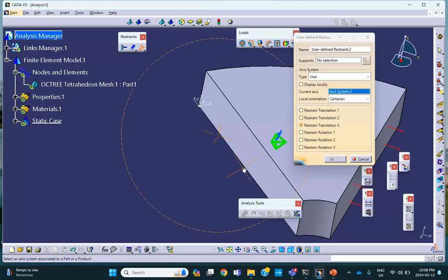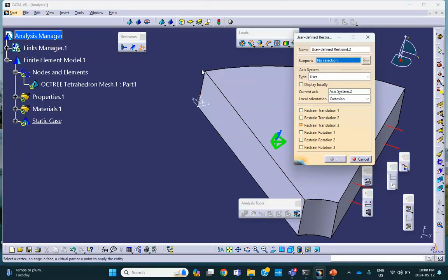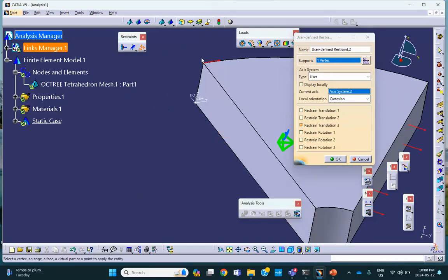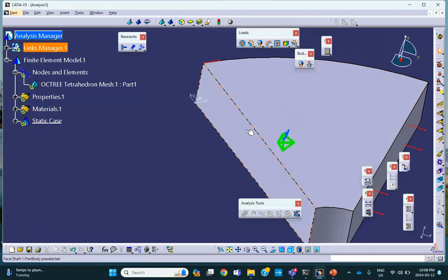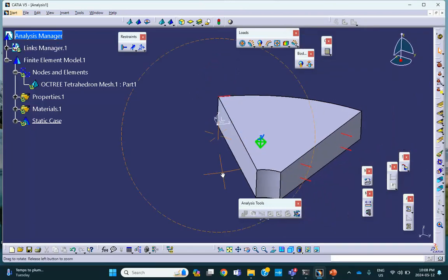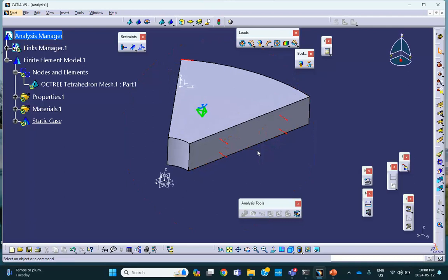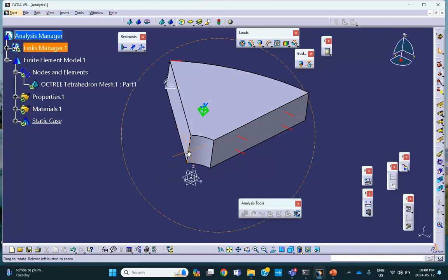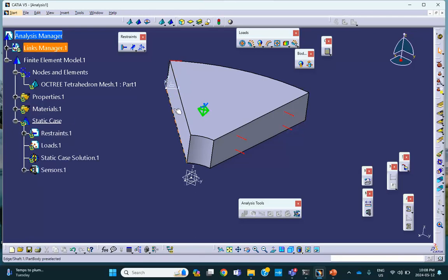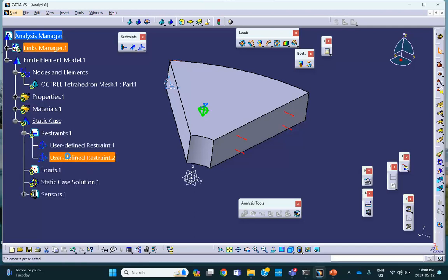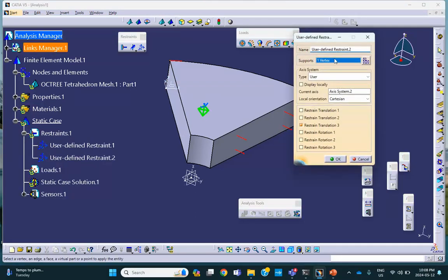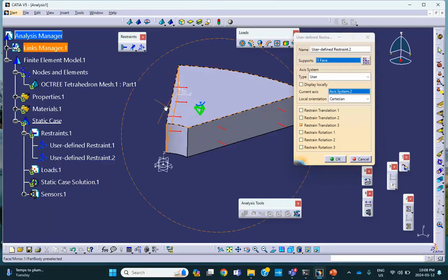And it says where. Okay, support is that corner point. For example, this corner point. It doesn't matter. That corner point, or this corner point, or this corner point. It makes no difference. We say, okay, good. All right. So this is, I'm not using any surface slider. Oh, I'm sorry. I made a big mistake here. I didn't want this one. I want the whole face. Oh, okay. So double click on that. Not this point. You can say remove support. I want all points there not to move, not that, only that point.